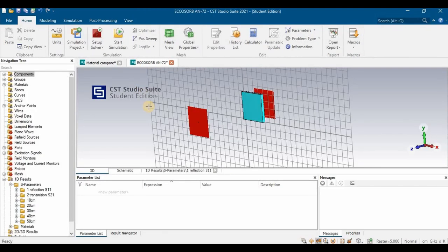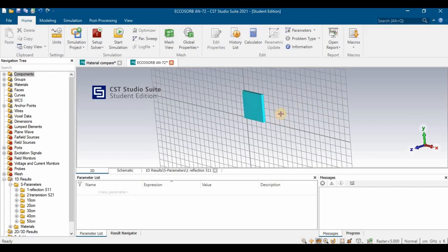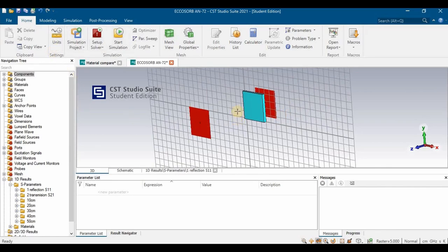So we can use it to continue the simulation, in which we can adjust the distance between the plate and the receiver port Z2. Imagine that this is the inside of a microwave oven. It transmits a signal to hit a power, and the rest is leakage power that goes outside. So we can test and measure the leakage power at different distances that we want. In this case, we are going to measure it from 10 to 50 cm.